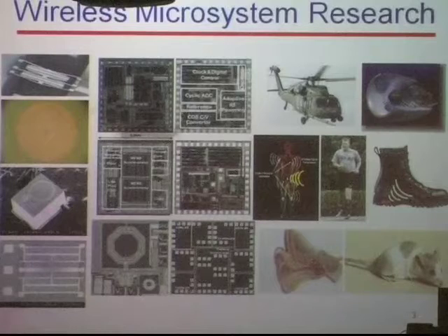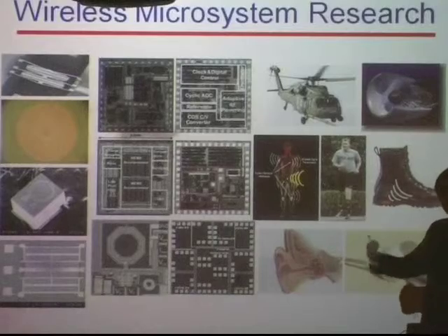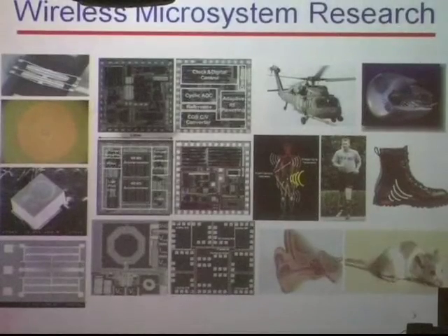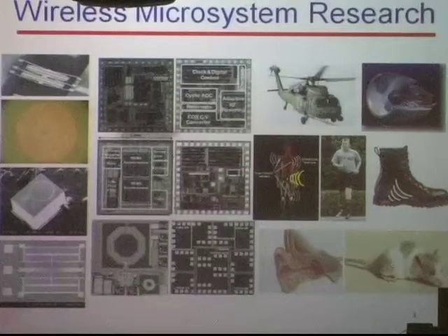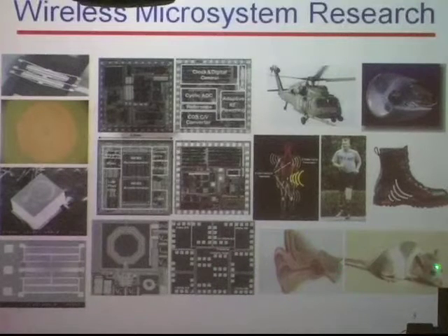if you do research in that area, you know that those devices suffer from drift. So if every step we make, we know when the velocity is zero, we can use that information to zero out the drift to achieve much better improved performance. And they also used it for various biomedical applications, for example, cochlear implant and a small animal genetically engineered mouse implant for various biological study.